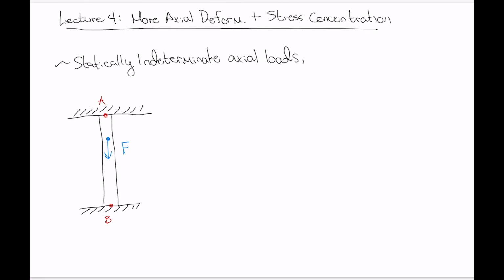So that requires getting our internal forces, and we can see that we're going to need our support reactions. Okay, so let's go ahead and try and get our support reactions. Let's draw the free body diagram of the object. So we've got load F being applied. There's our externally applied load, and we've got AY and BY.